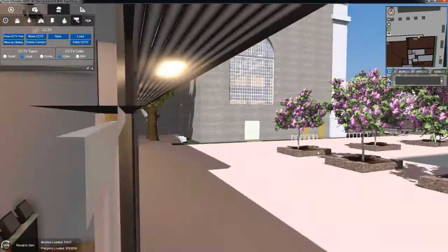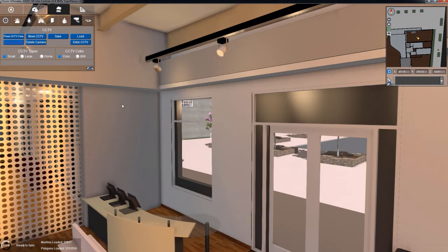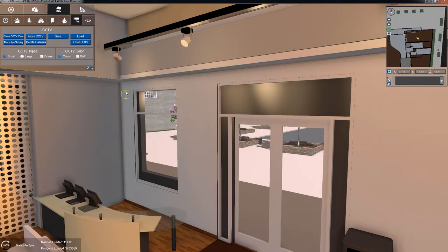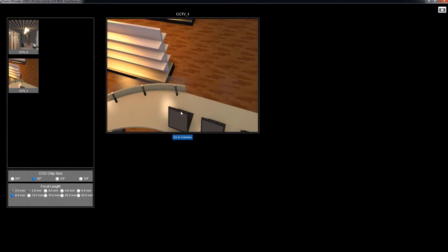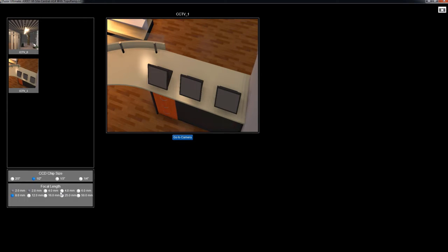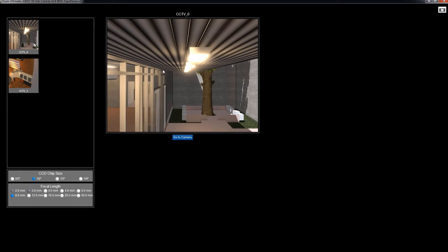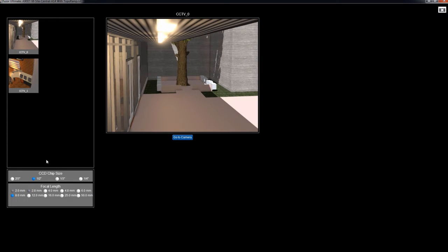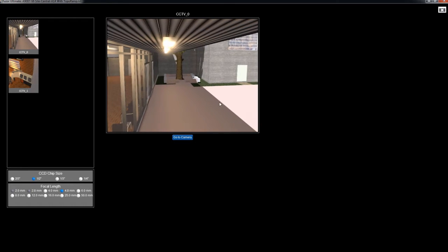And just one thing real quick. Another good place to put a security camera is right behind any kind of cash register. So I'm just going to place one more right back in here. Alright. And I'm going to go ahead and hit Enter CCTV. Go ahead and adjust those cameras. So obviously this one I want pointing down at the registers. I'm going to have to back that up a couple just so that if something's going on that's funny at the registers, both behind and in front, I can check that. And then over here for CCTV, I can check that corner. I'm going to back up a little on this one too, just so I can have a wide area on that. Later on, we're going to be able to display coverage cones also for these.